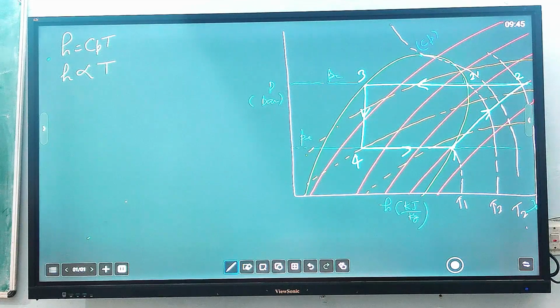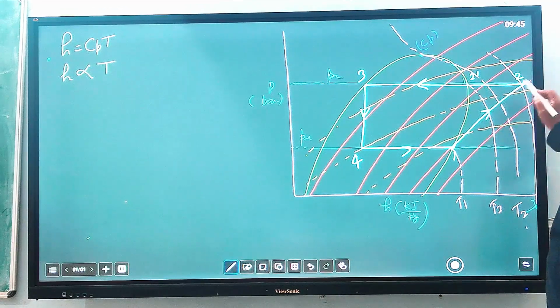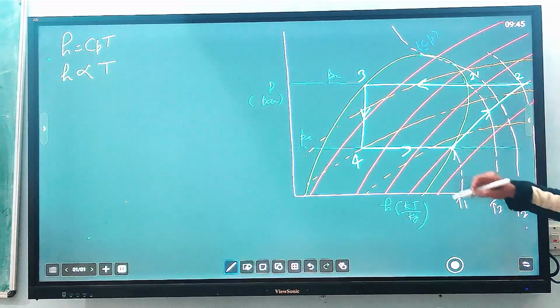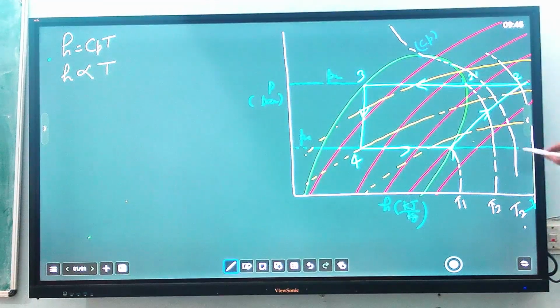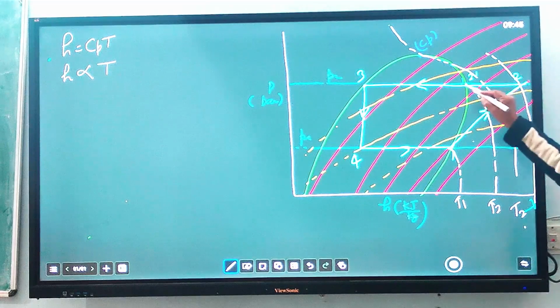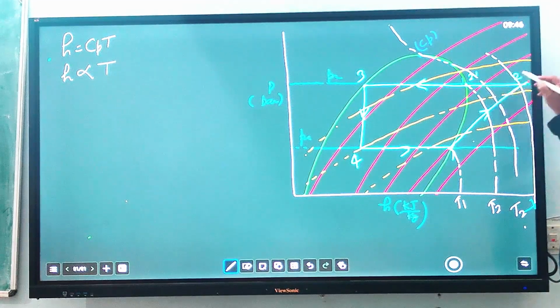the problem. So you see that 1 to 2, the vapor enters the compressor at fully saturated state, meaning fully in vapor state, and after compression it leaves the compressor at superheated state, and then it comes to the condenser. At this point, first cooling will take place at constant temperature.